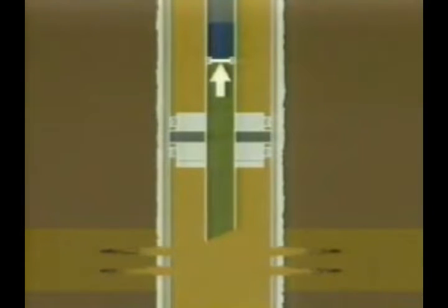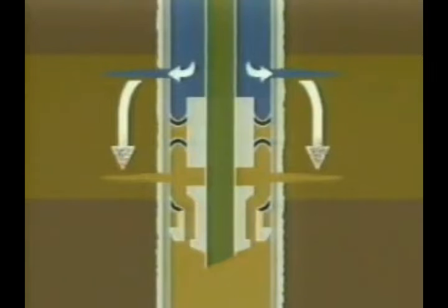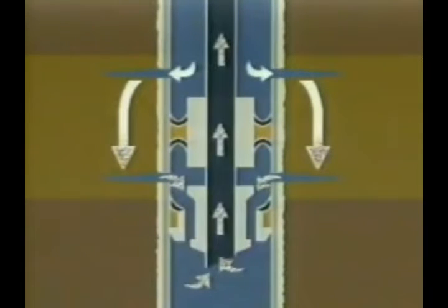Then, in the case of the perf surge technique, an underbalanced tubing string is run into the well and set with a packer. When a shear disc within the tubing string is ruptured, the perforations are subjected to a sudden surge of drawdown, expelling any debris that may be present due to the overbalanced perforating. In the perf wash technique, the conventionally shot perforations are washed using a cup assembly that forces clean fluid into one set of perforations and out of another.